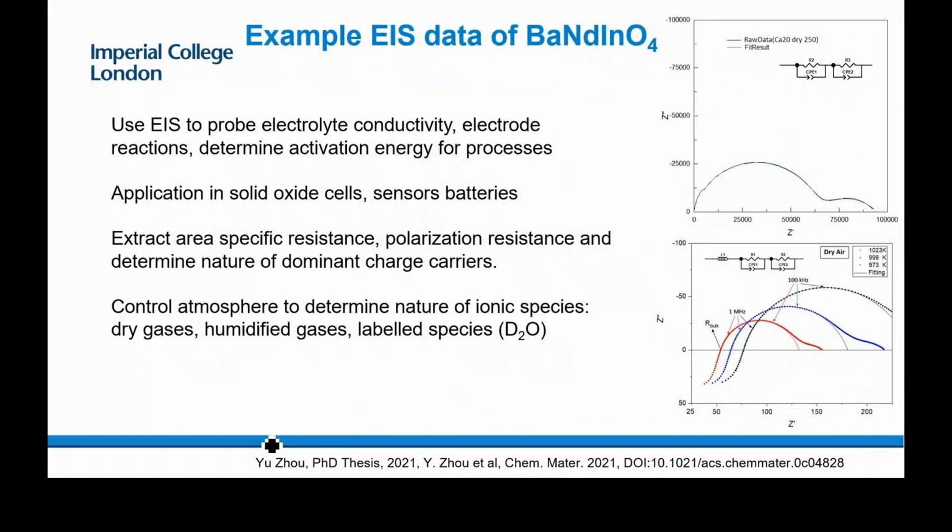High frequency is always at the origin, effectively, typically, and you just scan from low to high. Low frequency is at this point in the spectrum. Each of these data points will be at about 0.01 hertz, and you can scan from low to high, or from high to low. It doesn't really matter. It's just conventionally the way in which the instrument is set up. It starts high. The data collection times at the higher frequencies are relatively short, just a few seconds. As you get down to the lower frequencies, the time per point increases significantly.